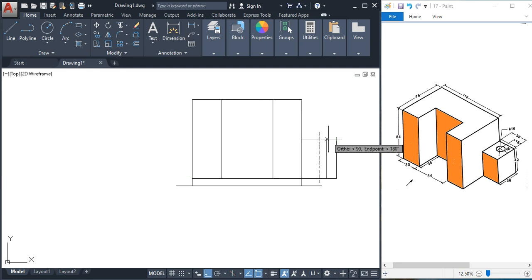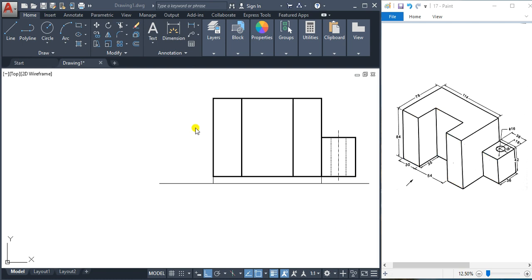And we have to draw a vertical line here, and once again we have to draw on the left side also, so we measure 8 and draw a vertical line here. This way, we will convert these two lines into dotted lines. Anyway, in the drawing sheet we directly draw the dotted lines. So this indicates the front view of this object. So let's darken the required lines here. Like this, we can draw the front view of this object, and now let us draw the top view of this object.